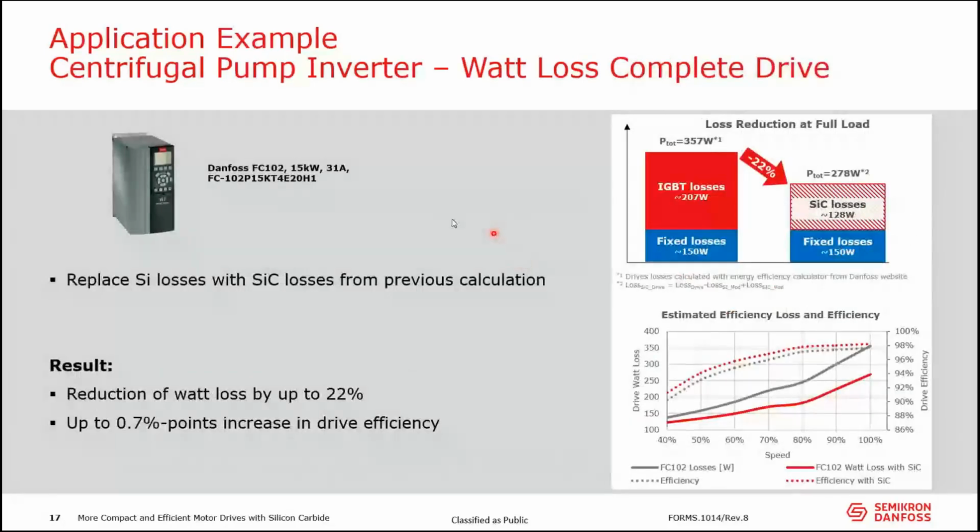Then I went one step further and thought, what would it mean in a real drive? And to do that comparison, I used this Danfoss drive here. I used that because there's a nice energy loss calculator on the website of Danfoss, where I can do nice calculations and do these kind of comparisons that I wanted to do. And what comes out here is the first thing, when I run the pump or my pump application that I used here at full speed, the energy, the losses would go down by 22%, which is quite something.